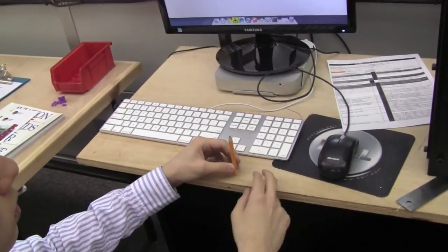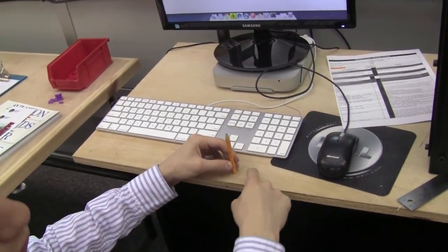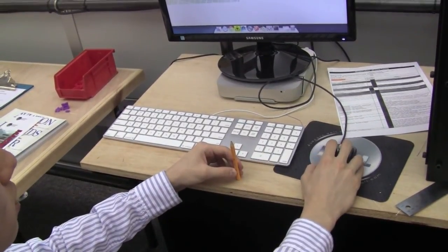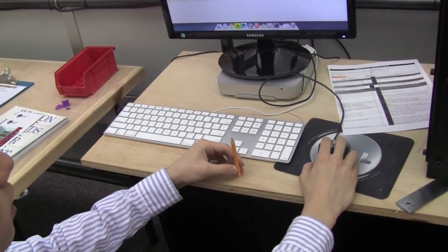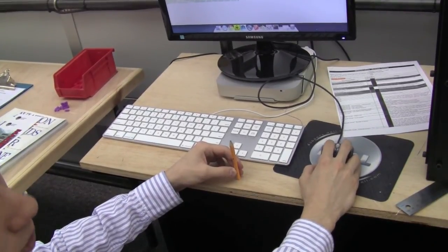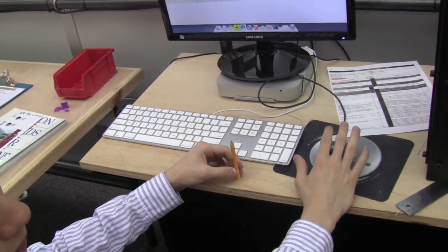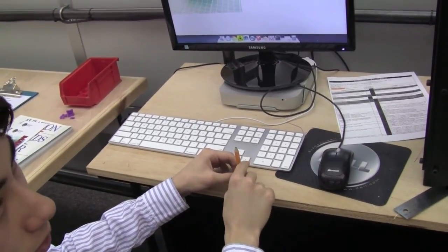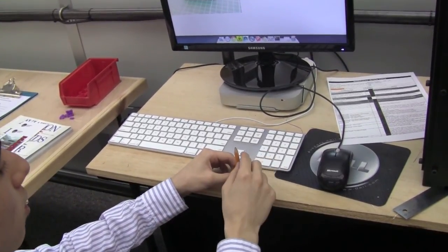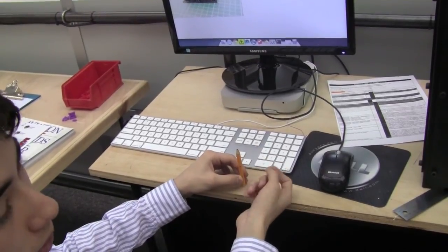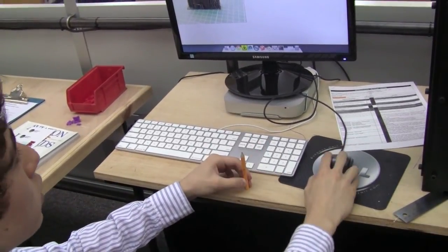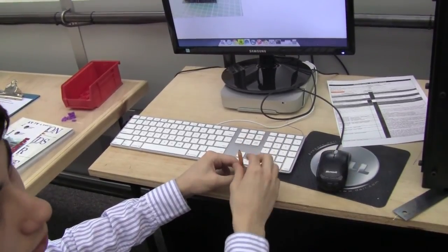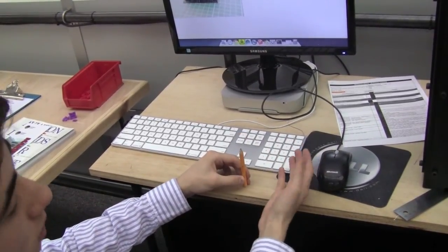So what the support does is it makes a scaffolding around your model, and it builds it all the way up along with the model. So that's what you see here. Here's the model, and for every layer of the model, it also makes a layer of support until it gets to wherever the overhangs are. Once it gets to the overhangs, there's this thin layer of plastic that was built by the support that'll let that overhang be printed, because then that overhang just prints on top of this thin material, and then it can finish the rest of the build with overhangs.